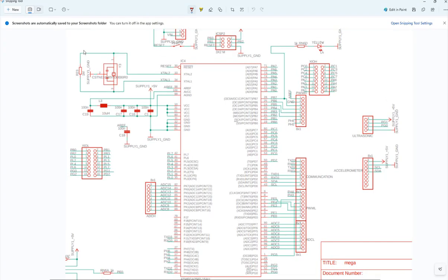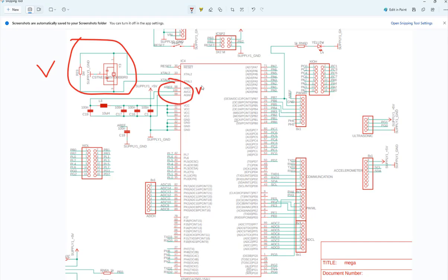So what do you need here? You need the oscillator. Power. This is power. VCC. All these things. You got another inductor here. Inductor doing what? Passing DC ground, rejecting AC noise. It'll be on the quiz, right? It'll be on the quiz.